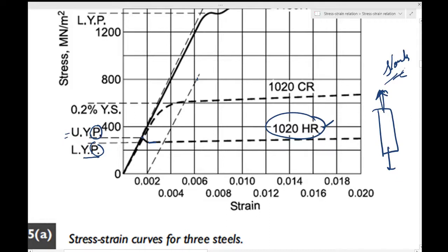You want to do it slowly, but your machine must have a number for how slow, and hence it changes a lot every time, even if you slightly vary this pulling rate. And that is not good, because it should be a material property. A material property depends on the material, not how you load or what dimensions you take. That is why it's not a good idea to use this one.